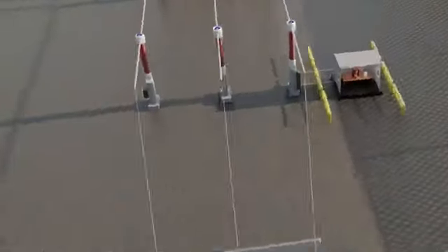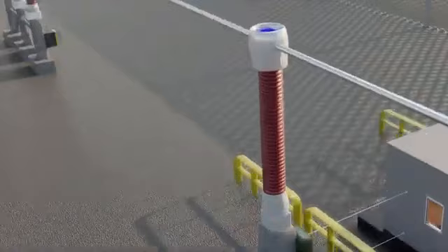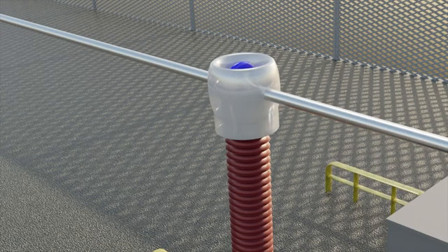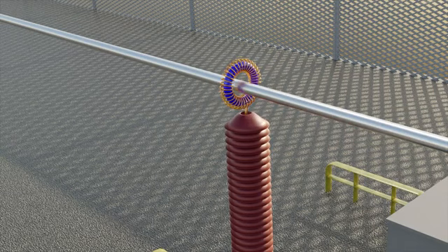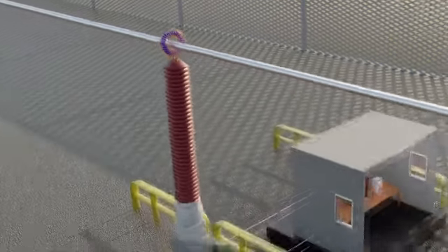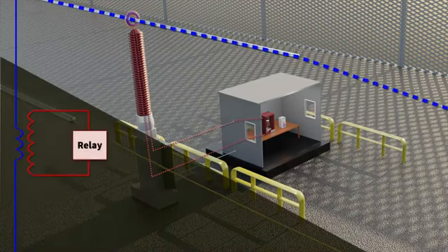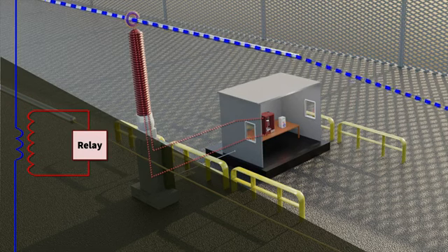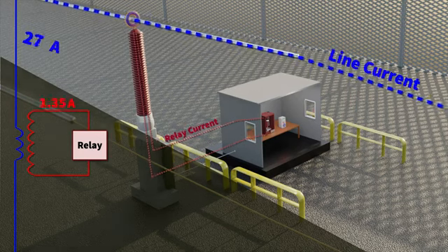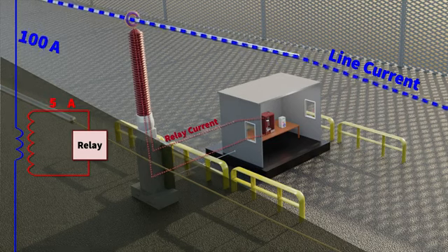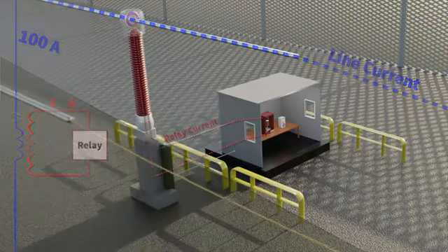The current transformer, or CT, has the ability to step down the current on the line to a proportionately lower level. This is absolutely necessary because the fault current is way too high to measure directly. Now, the CT is very much like a standard transformer, where the line current is the primary, and we can construct a secondary with the number of turns we require to step down the current. Now, in the electromechanical relays, this secondary CT current is actually fed straight into the relay and has a direct effect on its operation. More on that a bit later. But as you can see here, we know the line current because we know the CT ratio. So in this case, if 100 amps is flowing, we know that there's going to be 5 amps on the CT secondary.